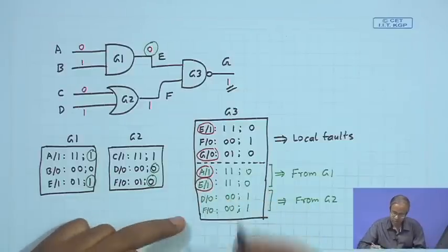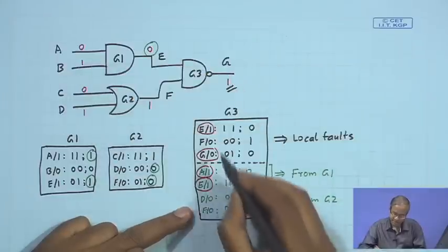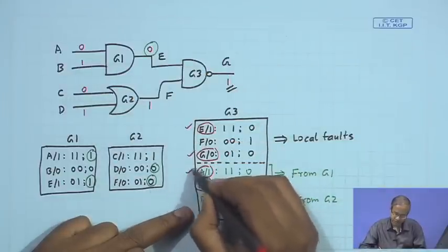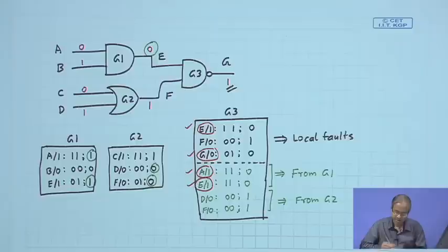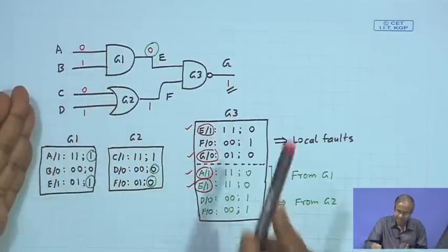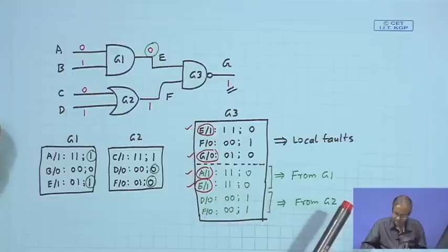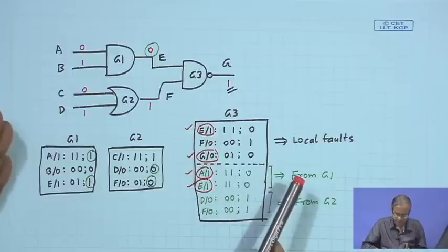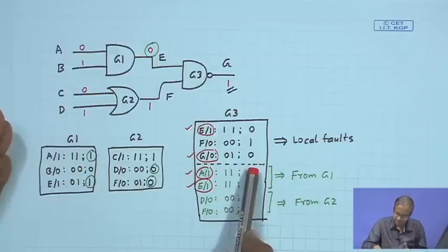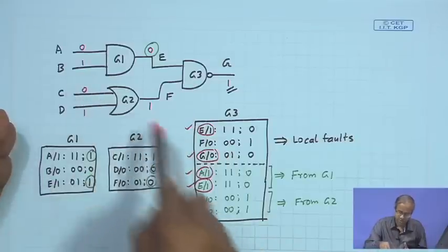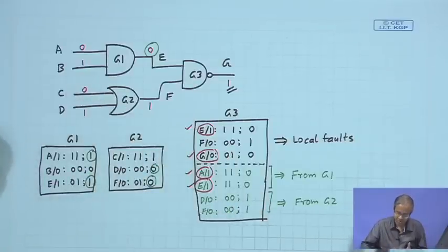So, you can conclude that this particular test vector detects these 4 faults, right. And when the second vector is applied, we follow a process which is very similar to the deductive fault simulation. Same way you proceed, same way you modified the fault list. If there is no event, do not make any changes, same way. Okay.